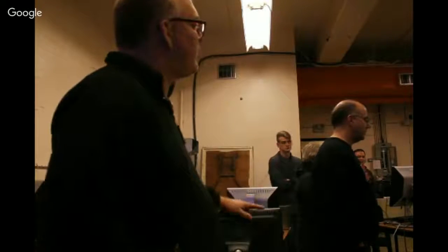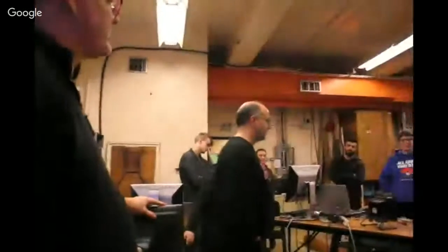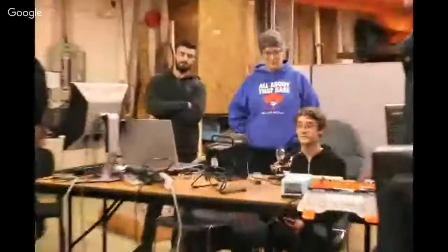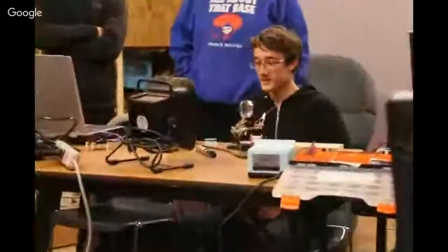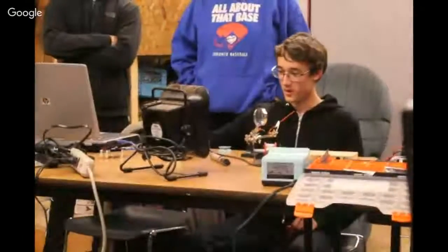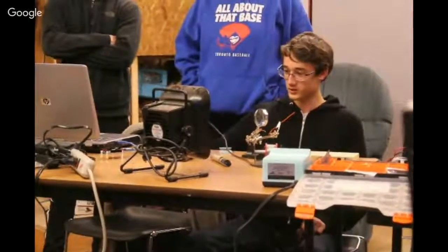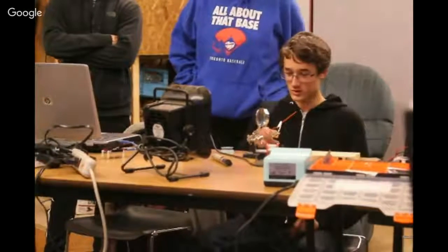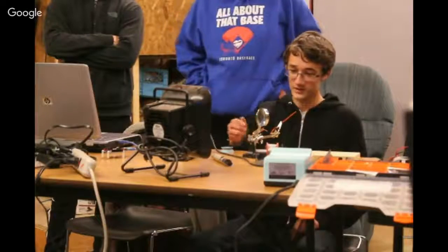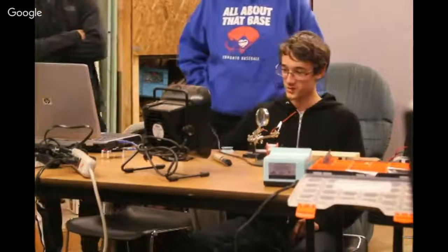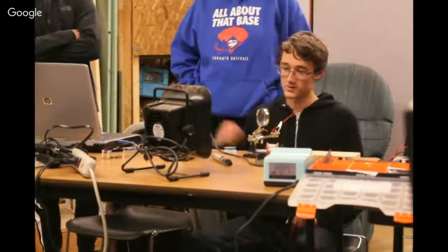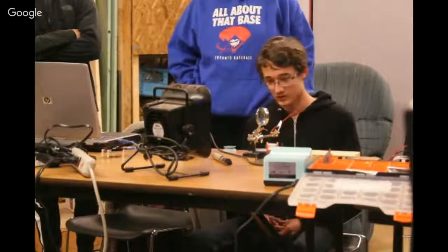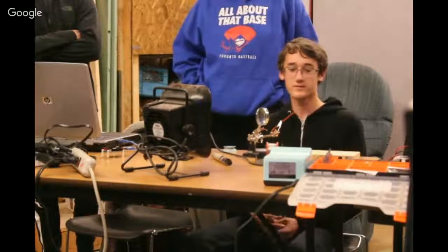Maybe Zach, you can talk a little about what happens when you come into the makerspace and the soldering iron is totally dirty and you can't get it to melt solder very well. What do you do? In that case, you take a bit of water, wet the sponge, and load that. When you're doing solder joints like this, every 10 or so joints, get any solder residue on the tip off of it.